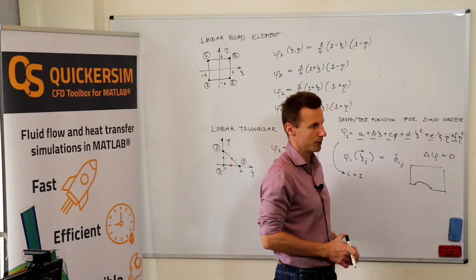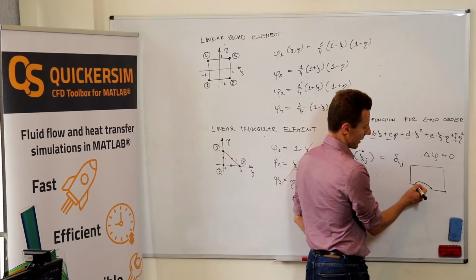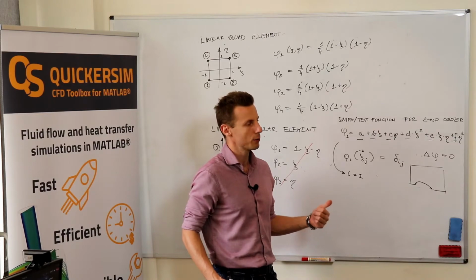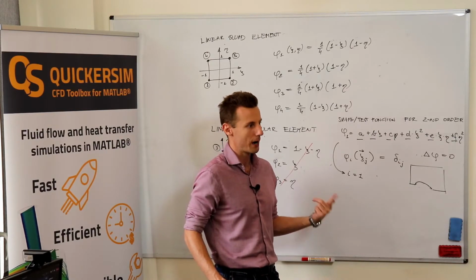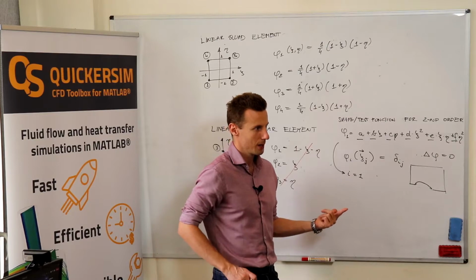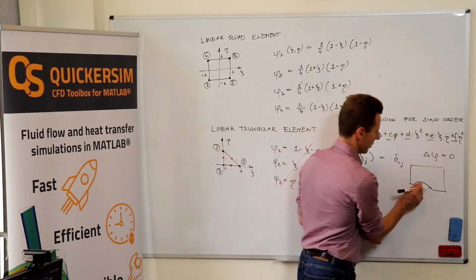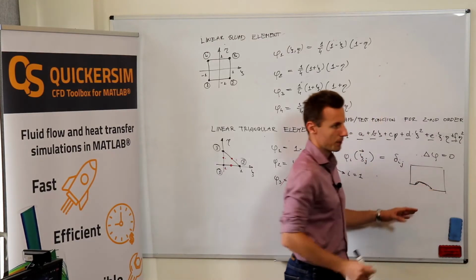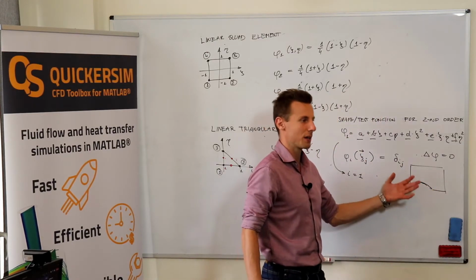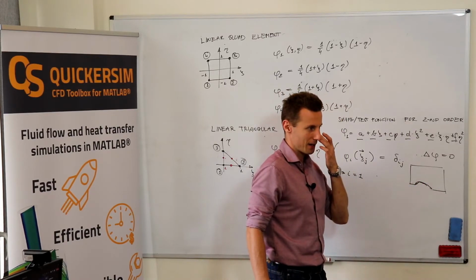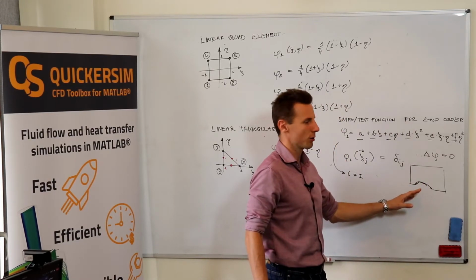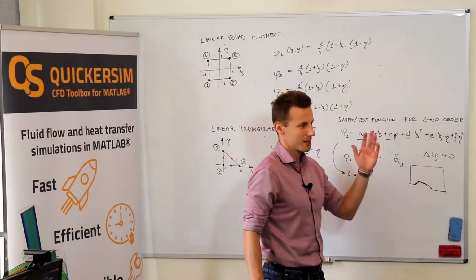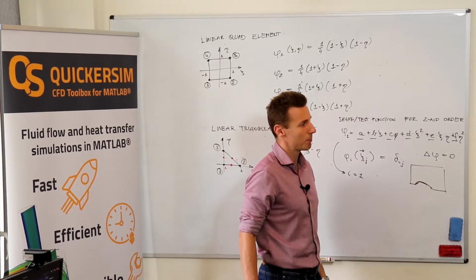above the airfoil. We've been doing that assuming that we either have a linear representation of the geometry or a high order representation of the geometry. And it turned out that if you use just linear representation of your geometry, obviously with higher order, you've got less and less elements. The conclusion was that if you've got linear geometry representation, then second order is the best solution.